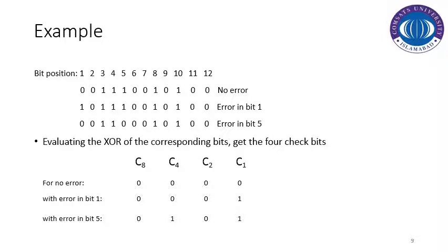operation between the parity bits and the checker bits, and because both have the same relationship for the exclusive OR operation, if the bit placements are the same, then the result of exclusive OR is 0. If there is flipping, in any case where the parity bits are changed, then in that particular case we are going to identify that bit placement contains the error.